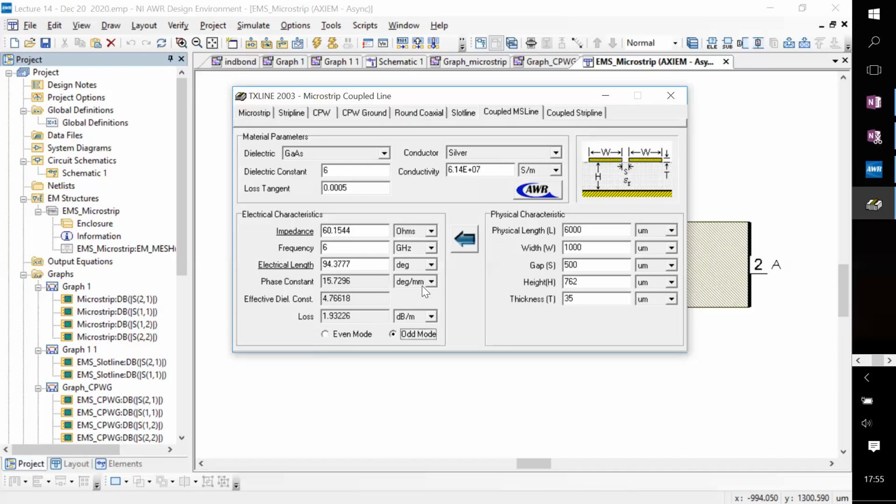And the phase is omega times delta t, where the frequency is the same. So the shorter the time, the smaller the phase accumulation, and hence the smaller the phase constant. Okay. So basically the even mode is slower, the odd mode is faster. But if one stares at this, could one have guessed that? So Priyo?